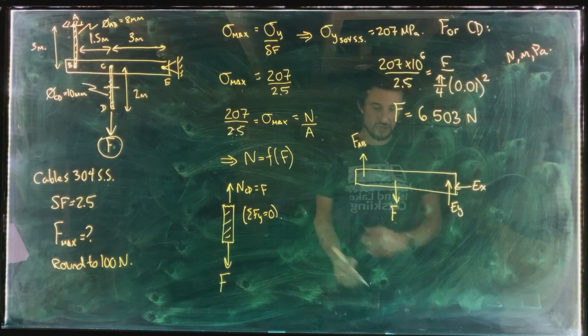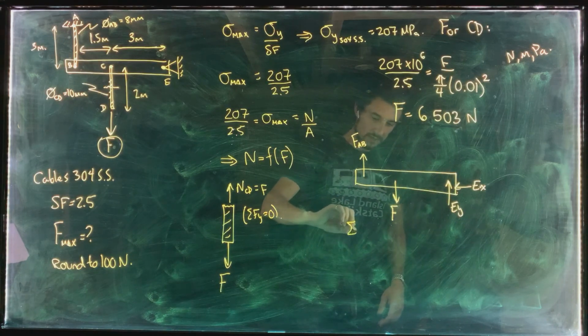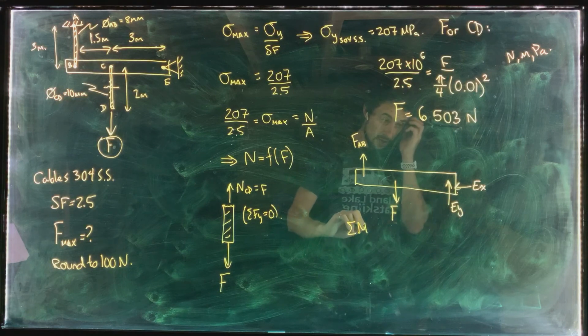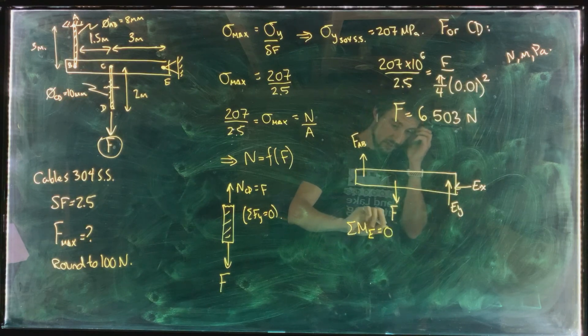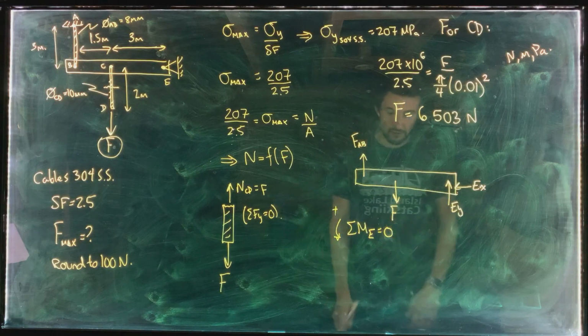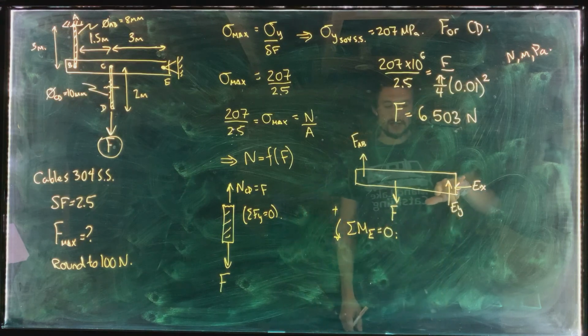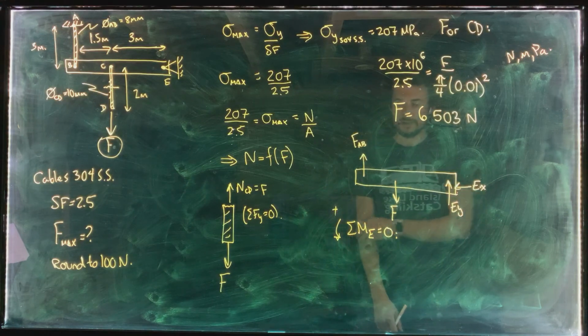And now what we can do is simply do a sum of the moments about point E equal to 0. And that gets rid of EY and EX here.